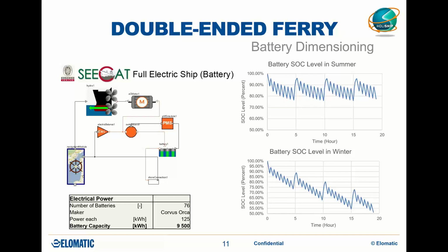And the negative side of batteries is that they are heavier and take more volume, especially compared to a hybrid version. The reason is that batteries' volumetric and gravimetric densities are lower than what an internal combustion engine and diesel generally have.